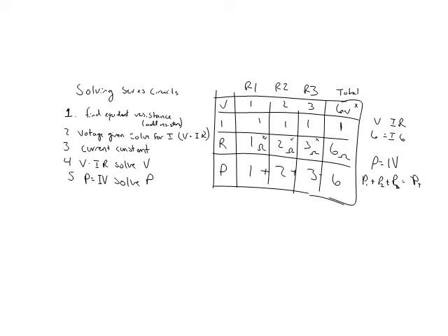A potential difference of 300 volts is applied across the system of resistors. So they just told us that our battery is 300 volts. We have resistor 1 is 40 ohms, resistor 2 is 100 ohms, and resistor 3 is 60 ohms. So I want you to write down this grid, fill it out, and solve. I want you to tell me what is the resistance of the system, the current, the potential difference, the power for each resistor, and the final power of the whole system, using this exact same thing that I just did. And if you look, A through E walks you pretty much through every single step.